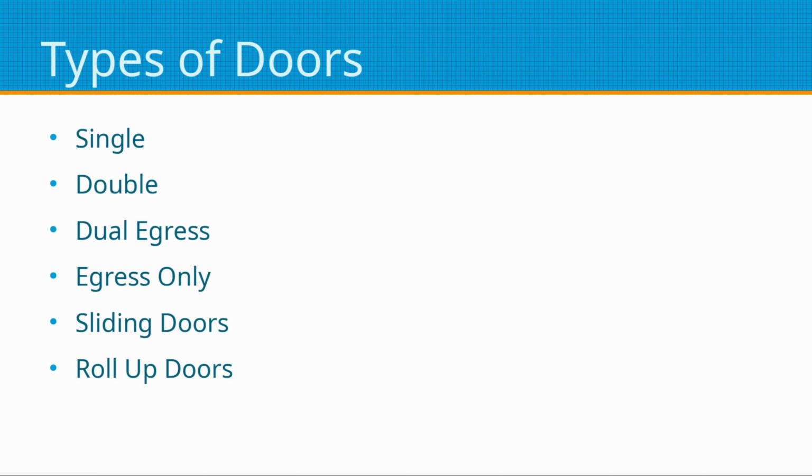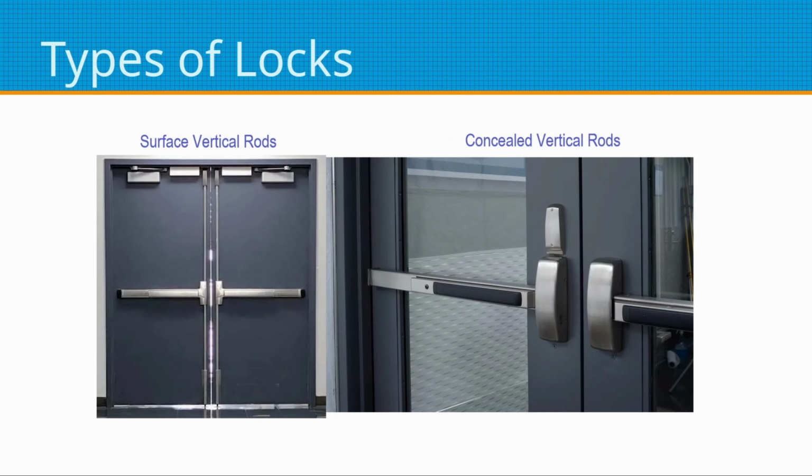But back to the talk about egress, you'll notice that those doors always have a sign on that says "in emergency, push to open." And so you can actually crash through that door, even though the door won't slide open. If you're on the inside and need to get out, you can forcibly push that door and it will swing out. Roll-up doors, often there's the same type of deal, some sort of an interlock inside the motor that opens the door up. You could also potentially have some sort of a magnetic lock to keep them secured.